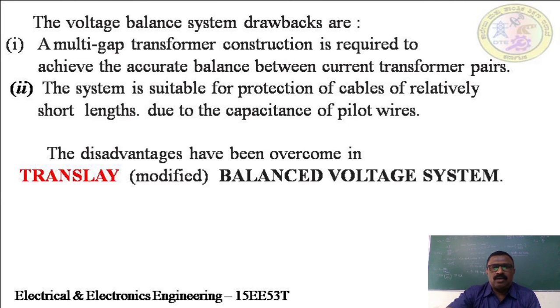So even this voltage balanced system has got drawbacks. One, the multi-tap transformer construction is required in order to achieve accurate balance between current transformer pairs. So the multi-tap transformer is essential in order to balance the accuracy between the two CTs, or the CT pairs. The system is suitable for protection of cables of relatively short length due to the existence of capacitance in